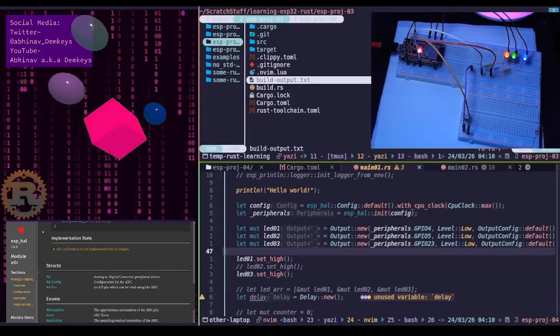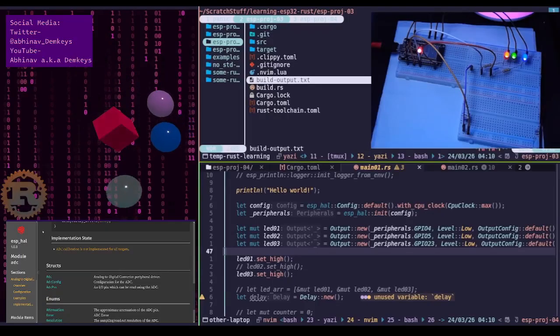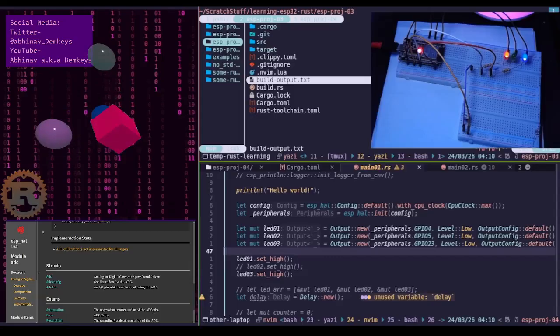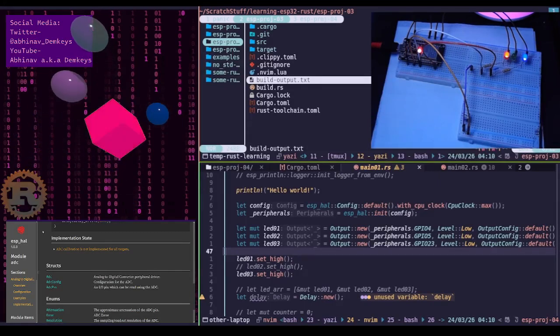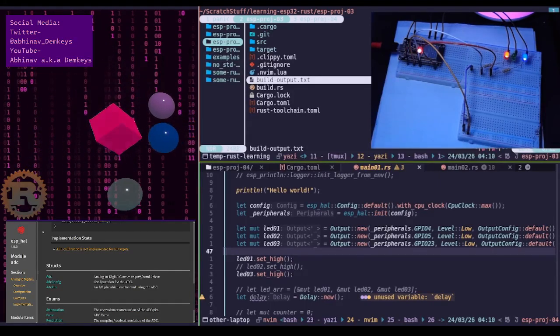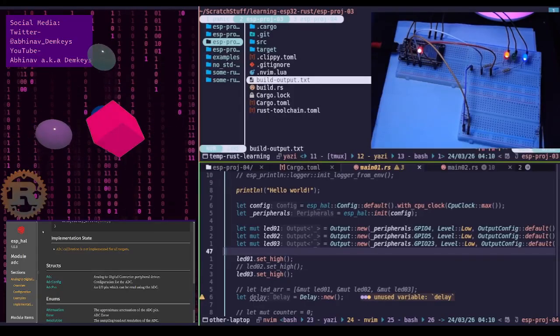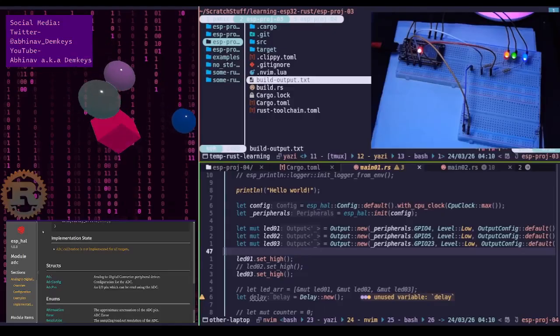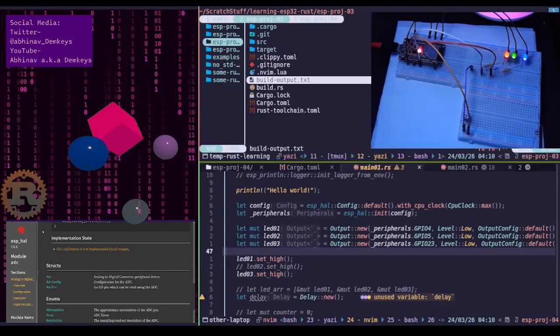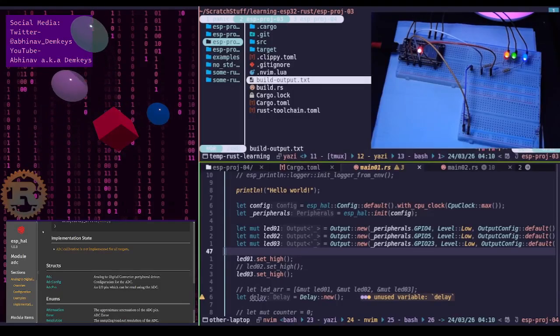If you choose to ignore calibration right now, your learning experience will be mostly unaffected, provided you keep a few things in mind. The good part of the experience: logic remains the same. The code you write to initialize the ADC, select a channel, and trigger a read is identical whether your chip is calibrated or not.